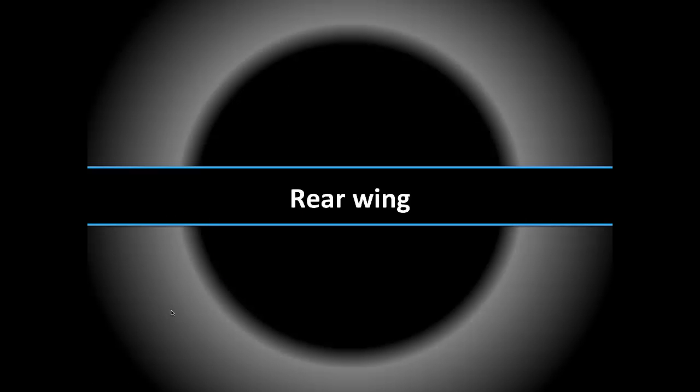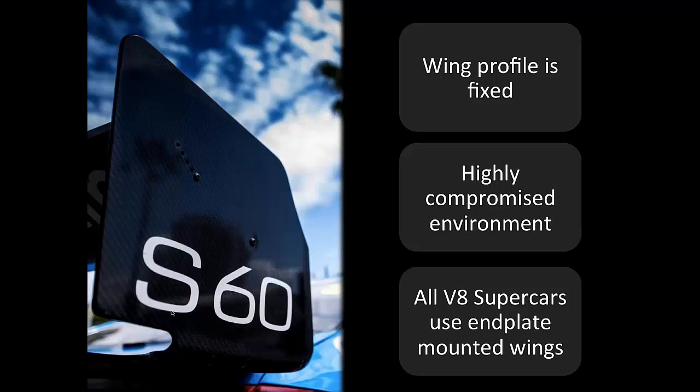Onto the rear wing, and this is something you'll see on every boy racer on the road, not that they know exactly what they're doing with the rear wing. So with a V8 Supercar, or in the Supercar series, wing profile is fixed, so you can't change the wing's onset angle, leading edge onset, to account for flow effects caused by, number 2, the highly compromised environment where the wing is sitting behind the glass house of the car. So your airflow is always changing at different speeds.